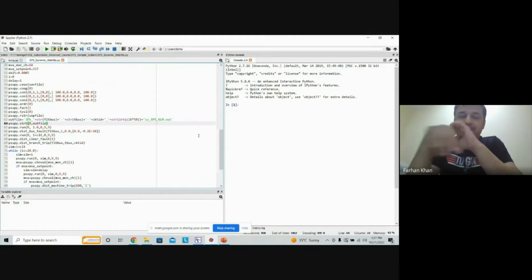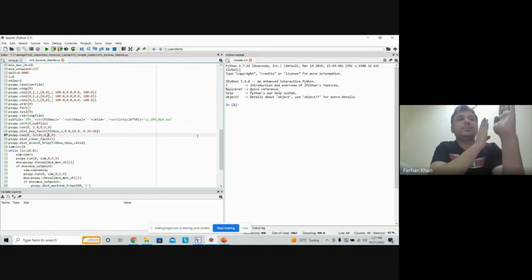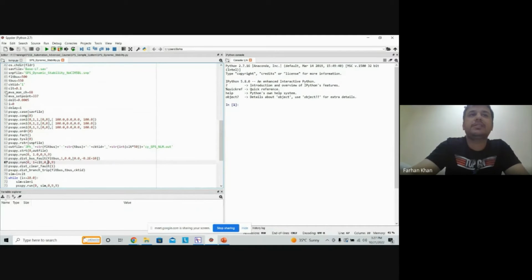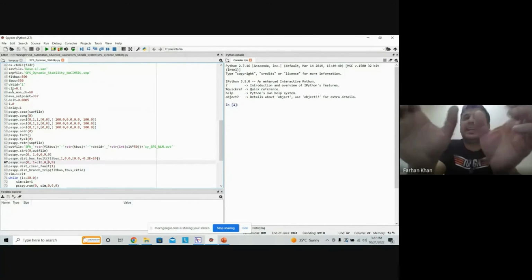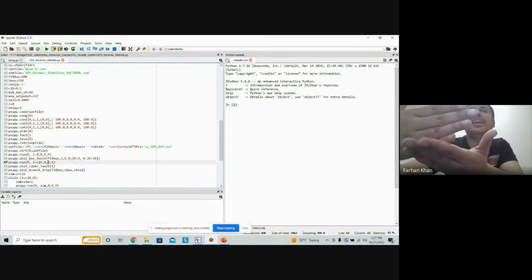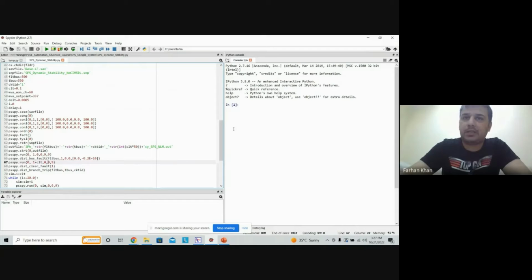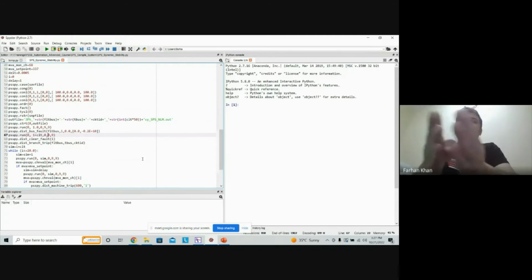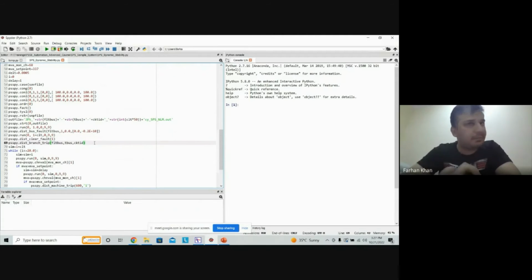So running the simulation for 1 second, then creating a three-phase fault. And because my simulation is at t equal to 1, I have defined my clearing time as whatever I've defined. In my particular case, I have defined my clearing time as 0.1. It is not critical; this is the normal clearing time, whatever duration after which you want to clear the fault. So that is why I'm using 0.1. My simulation is already at t equal to 1, the clearing time is 0.1, so I will run the simulation up to 1.1 seconds in this case. Then I clear my fault and then I trip my particular line.